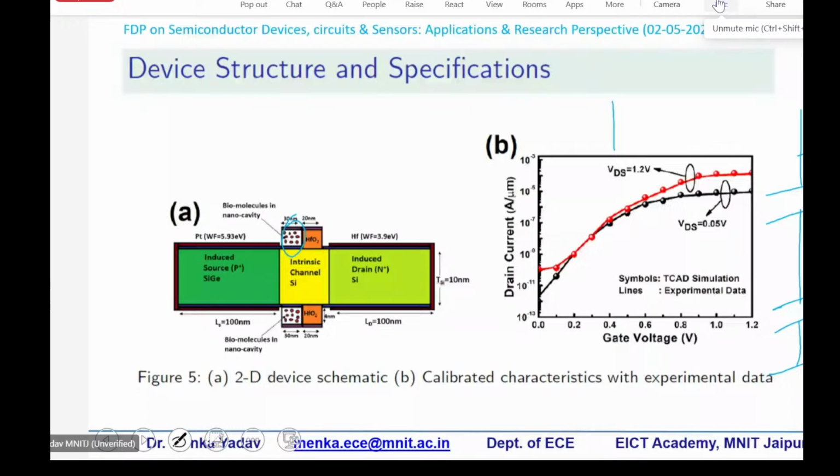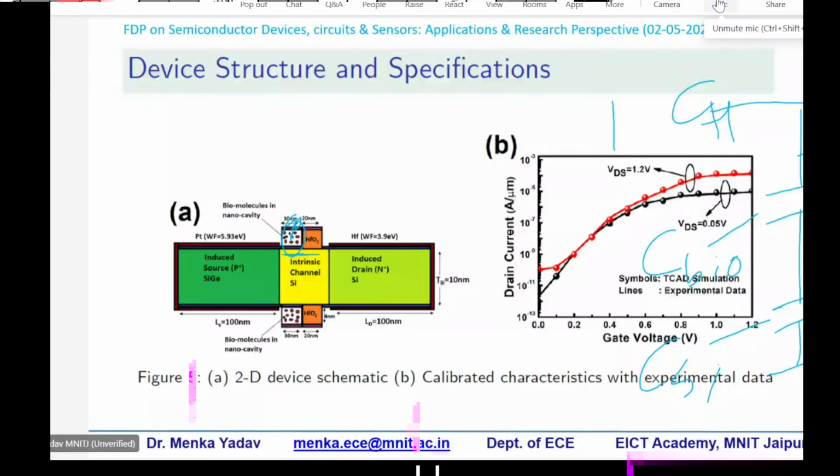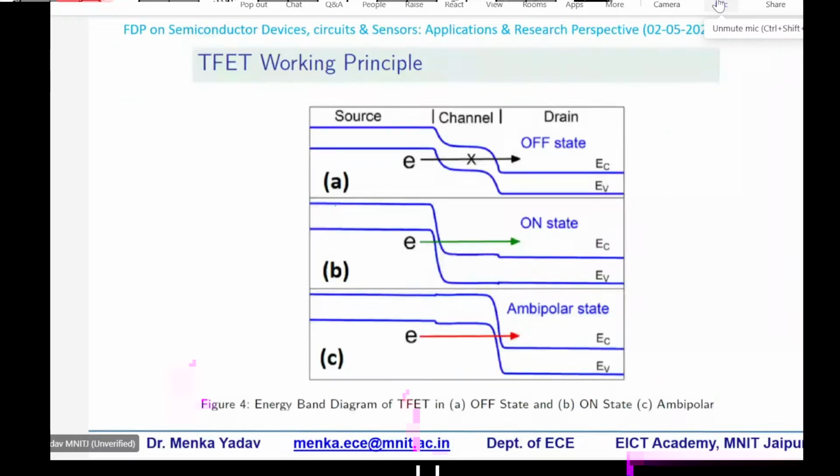So depending on this, let me give the name C-bio to this, C-SiO2 to this, and this is C-HfO2. Okay, so the equivalent oxide capacitance COX will be a combination of all these capacitances, and this effectively creates the band-to-band tunneling, because the energy band diagrams are modulated with the help of the gate, which is taken into consideration through this COX. The energy band diagrams were somewhat like this. In the normal conditions, it was somewhat like this.